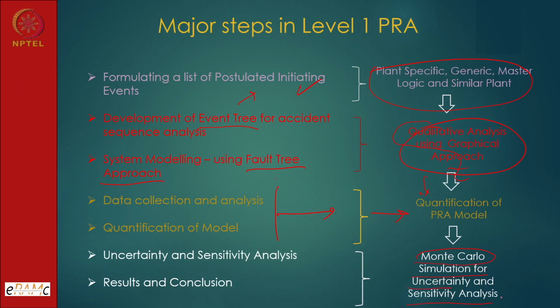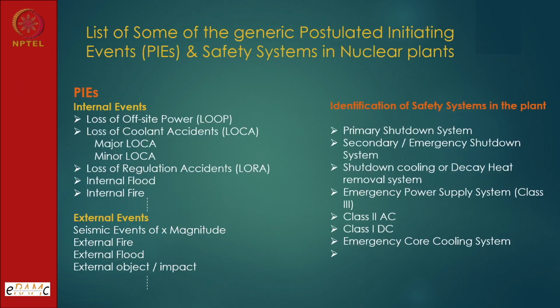So that means when we do a PRA analysis, we use Monte Carlo simulation, and along with that the Boolean logic, which provides the logic for reducing the fault tree, because it is a very computationally resource intensive exercise. So these two are very important. One is Monte Carlo simulation, and the other is reducing and getting the list of minimal cut sets along with their quantification. And those cut sets represent the major results from PRA, apart from the integrated statement of risk from the plant.